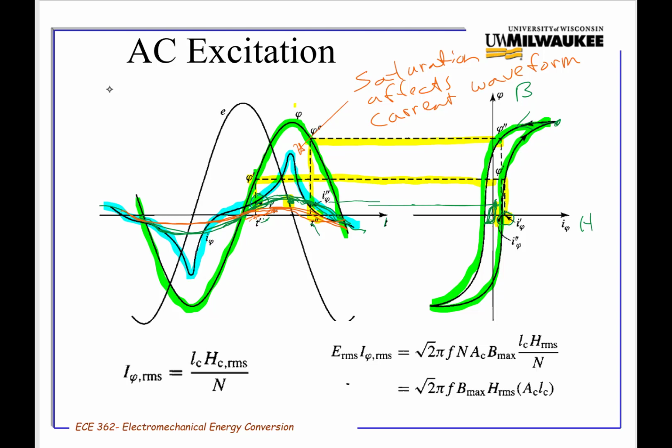Number two takeaway from that is if we're looking at designing something and we're trying to draw correlations between what we think these signals look like and the points that we're measuring on a BH curve, once we get into the saturation, everything becomes very nonlinear. So in saturation, you're in a nonlinear situation.